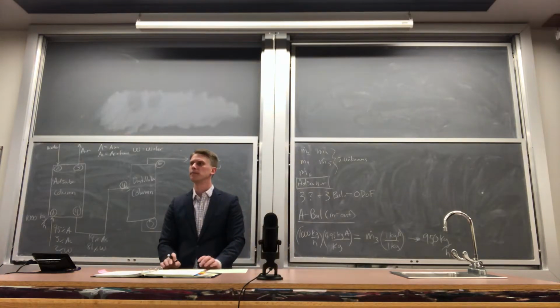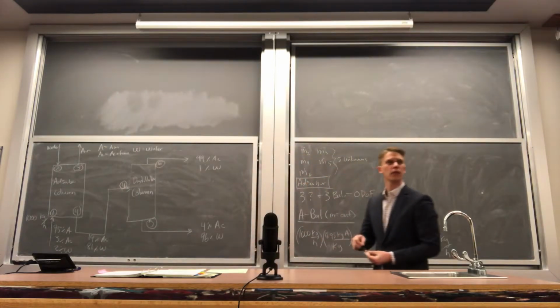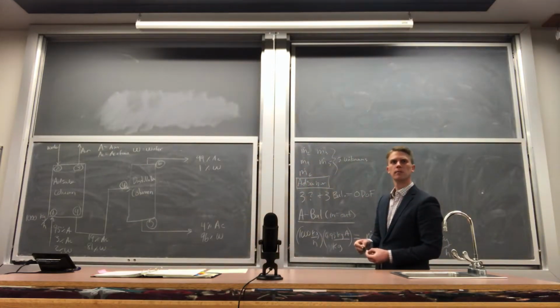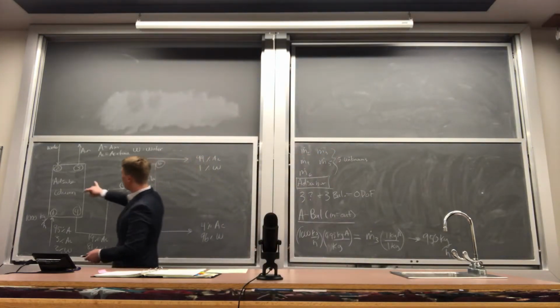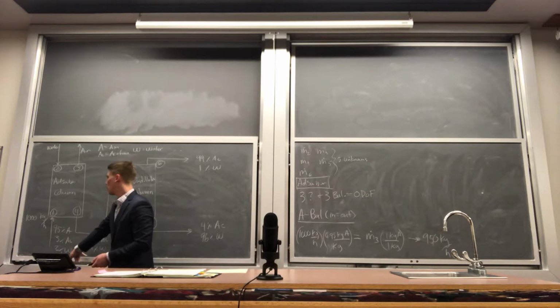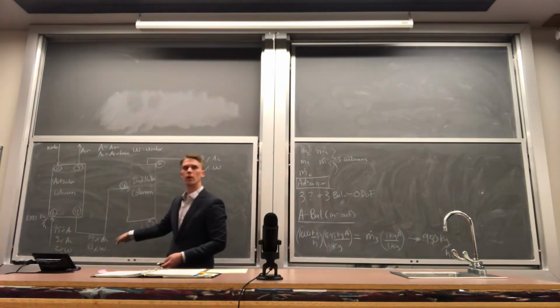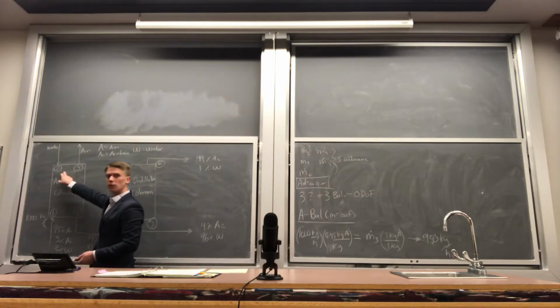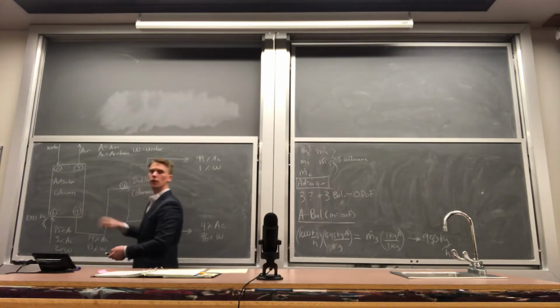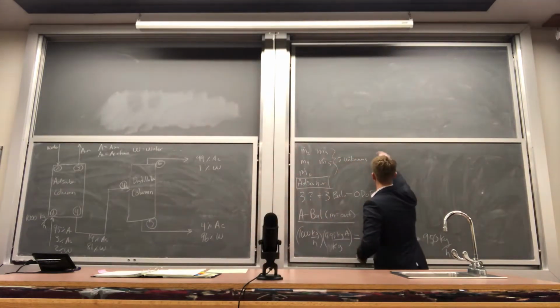What one should we do now? Acetone. Why acetone? Let's break this down just so we can think through every step. It's completely defined. Again, same thing as with the air: the acetone is only involved in 2 streams. Since stream 1 is fully defined, and stream 4, we should be able to get one equation and one unknown. Water, on the other hand, has 3 sources with 2 unknown flow rates, so we'd have a degree of freedom if we tried the water balance. So let's do the acetone balance.